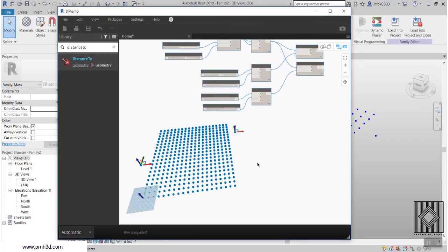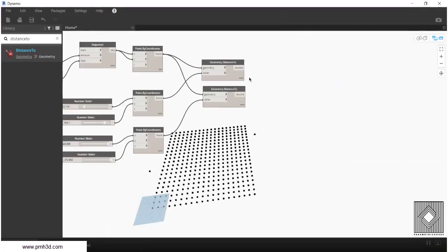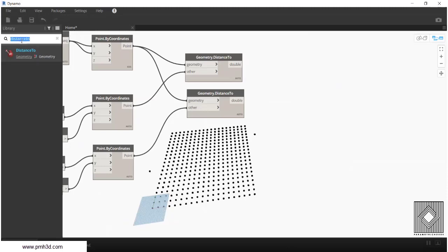Okay. I wanted that software to show you, but I guess it does not work on the Dynamo, so I have to install something so I can show you the distance. So this point is going to have two distances, one from this attractor and another one from this attractor. So we have to decide which one is nearer, and this will be the smaller one. So we can simply go here and search for minimum.